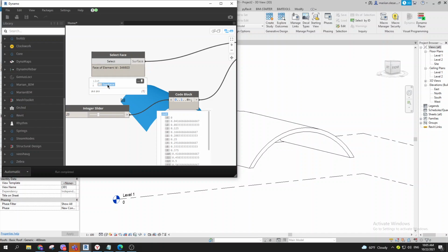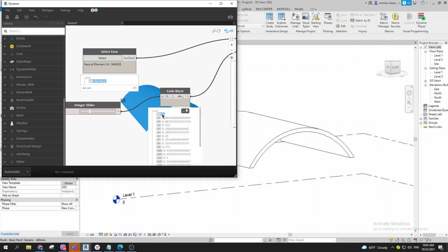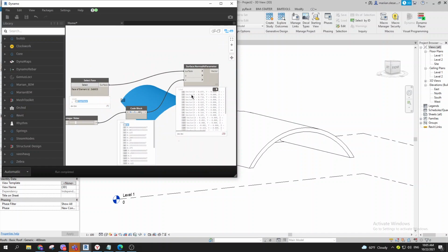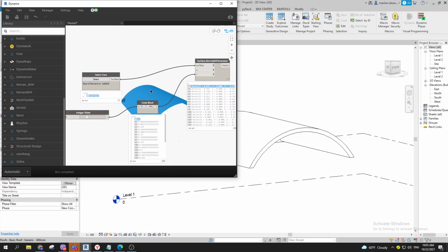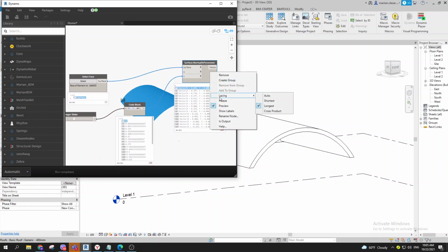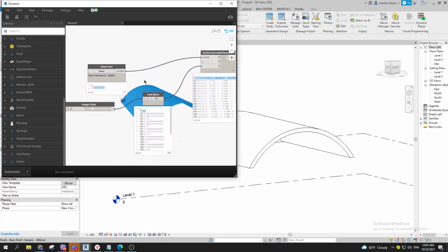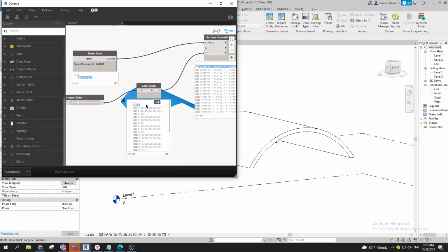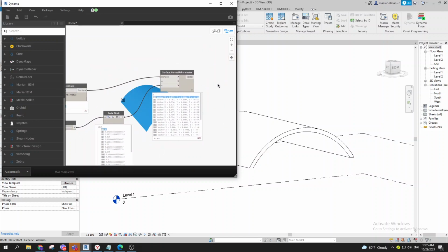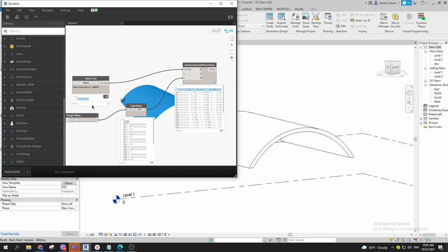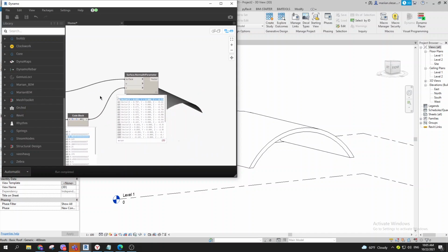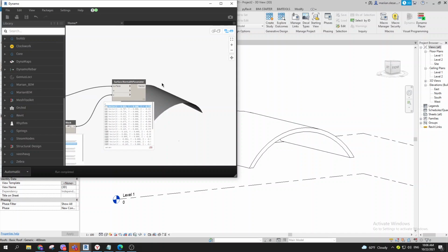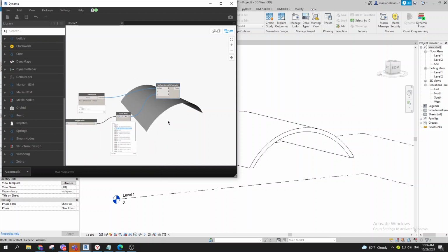It takes this surface and connects it to 0, and we get a vector on the 0, and that stops. By right clicking, going to the lacing and setting it to longest, it will make sure that this one surface goes through all of the elements: surface to 0, surface to this number, surface to this number, and that will give you vectors. Now the main question is how we can visualize them.